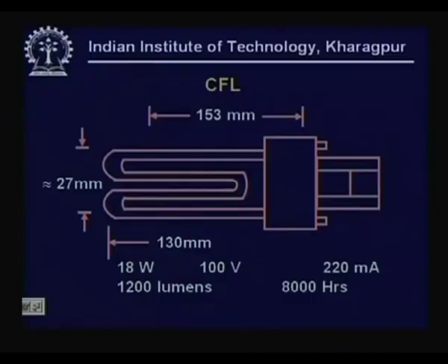The only one objection with this kind of lamp may be that the envelopes have not improved to that extent, in the sense, unlike a conventional fluorescent lamp, the light is not comfortable and the glare levels are high, and therefore, as it is found to be used in a naked form, it should be avoided. They are good if they are used together with proper diffusers, or when placed in recessed luminaires, that is recessed holders in the ceiling, they are very good.